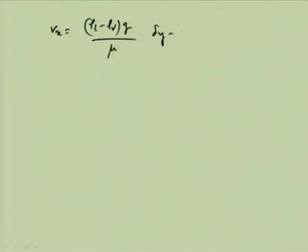Now, if we have a velocity profile of this kind, Vx is equal to (rho L minus rho V) g by mu into (delta y minus y square by 2). So, this is the velocity profile we have discussed.